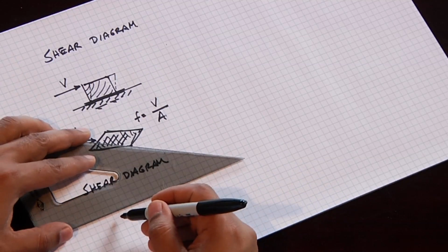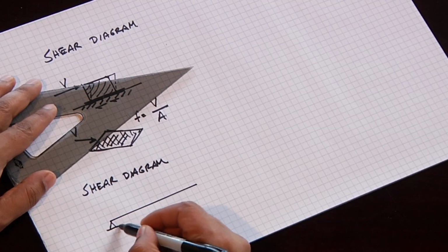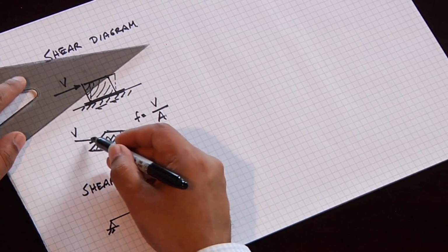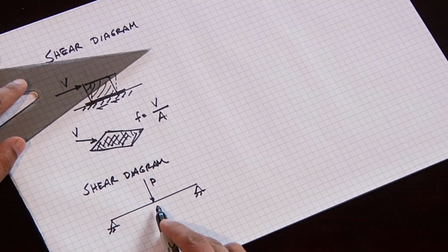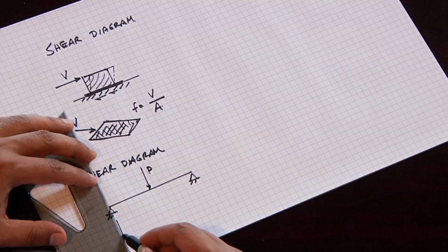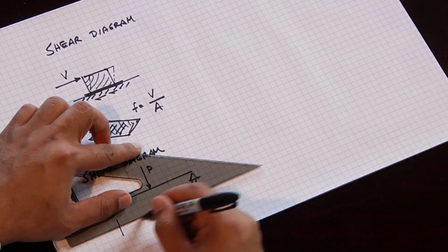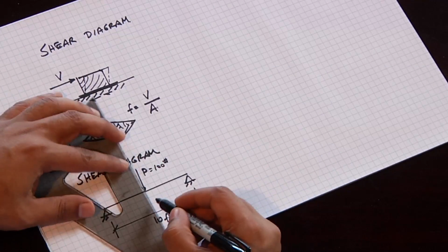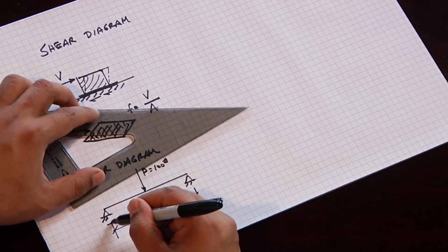So when we think of a shear diagram, and we're speaking specifically of a beam, we are graphing the distribution of that shear stress across that diagram. So let's take an example of a very simply supported beam with a concentrated load at the center. And the first step is, and we'll put some numbers on here, we'll say that this is a 10-foot span. We'll say that this is a 100-pound load, and it's equally distributed, so we'll put it at the center at 5 feet.